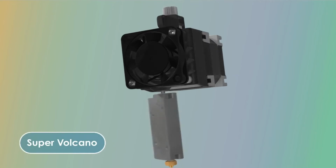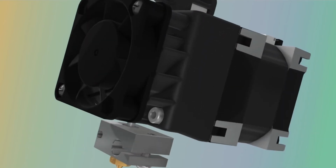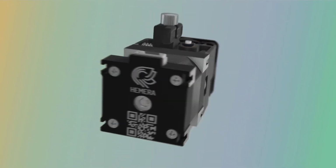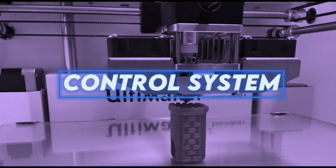If the difference is too great to make small compensations and adjustments, the interface will display an error message requesting that the operator run the manual build platform calibration process to improve the baseline calibration before trying again. Together, the results of both of these activities, the end stops identifying the true zero points and the plate calibration probe ensuring that the nozzle will always be at the right distance from the physical plate, establish the build envelope, and all is set for the print to begin.